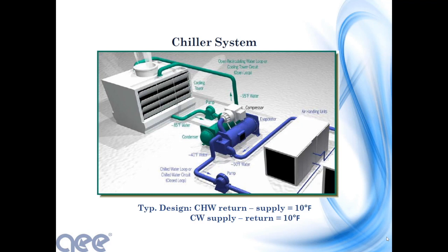So this is then your whole chiller system. As I mentioned before, the pipes that come out of the condenser of the chiller flow to a cooling tower. What a cooling tower essentially does is take that water coming off the chiller, typically around 90, 95 degrees, and spray it on the top of the cooling tower, where you have a fan that blows up and draws air through and cools down the water. So if the outside air is, say, 98 degrees and the wet bulb temperature is 70 degrees, you can typically get that water down to 5 to 7 degrees above the outside wet bulb temperature.